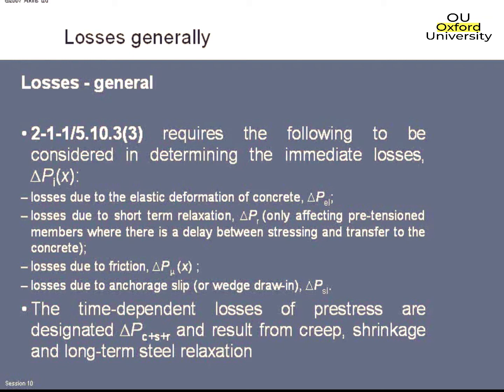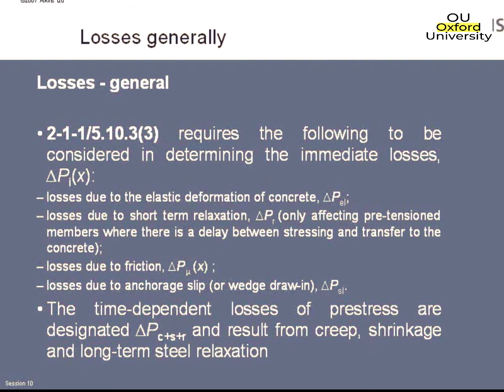So post-tensioning, that's normally part of the contractor's standard anchorage equipment, and there'll be some quoted slip when you transfer the force. For pre-tensioning, there will probably be some slip in whatever equipment's being used, but that's the contractor's problem. It's not an issue for the designer. We don't need to worry about that. When we specify force, we expect the contractor to have factored that out. And then long term, after we cover the short term, we have to calculate the losses from creep, shrinkage and relaxation.